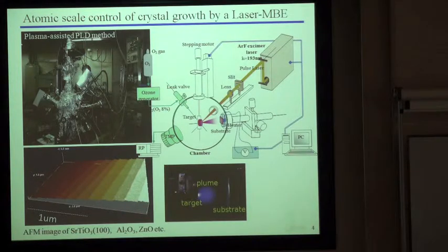They have a very high quality. And anyhow, for depositing zinc oxide, we treat these substrates using O2 and high temperature annealing treatment, and of course chemical operations also, to make an atomically smooth surface and deposit the film on these substrates.